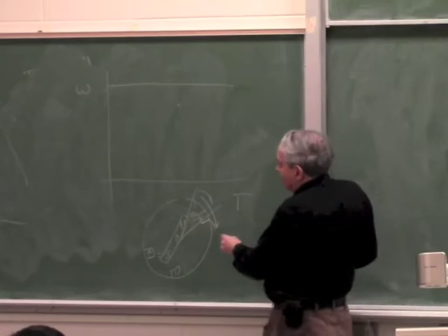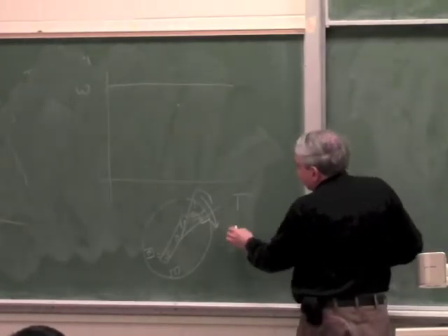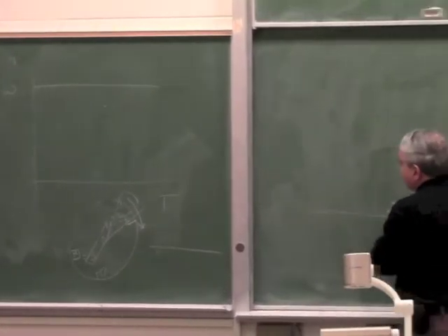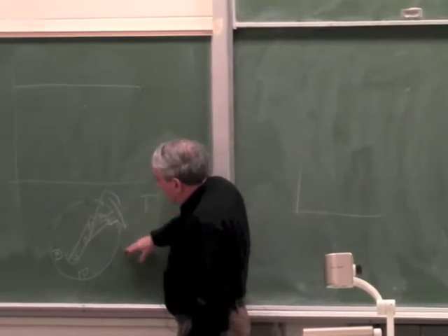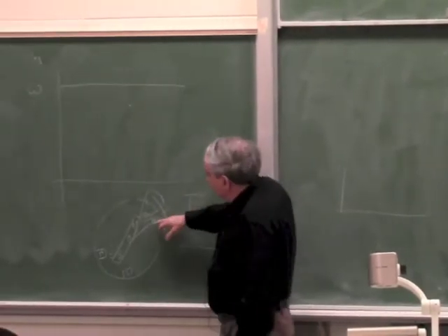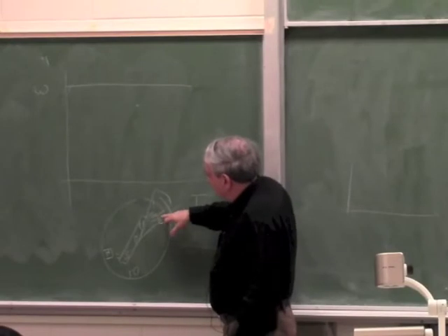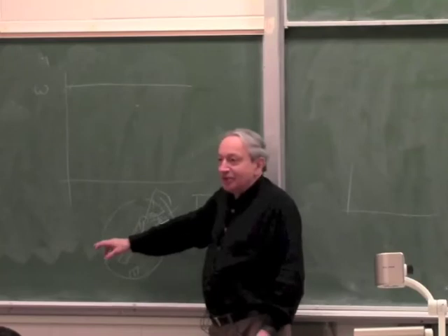So this power angle can only go up to 90 degrees and then becomes unstable. Now the reason is that it's clear to everybody that if the power angle went to 180 degrees, the torque will be 0, because at 180 degrees, instead of attracting, it will repel. If this S ends up here, instead of attracting, it will actually repel.